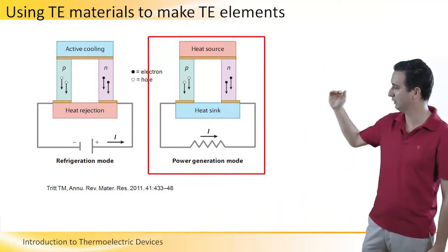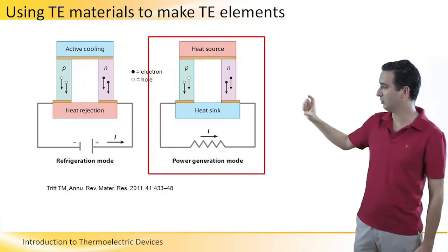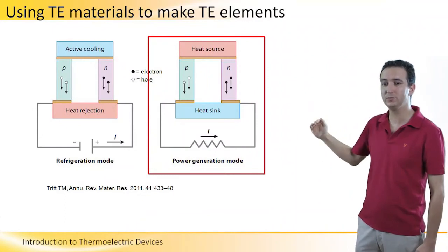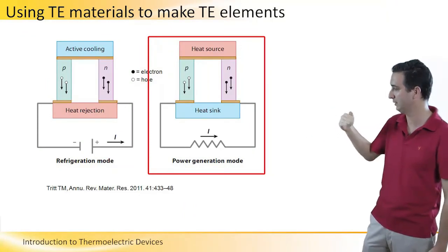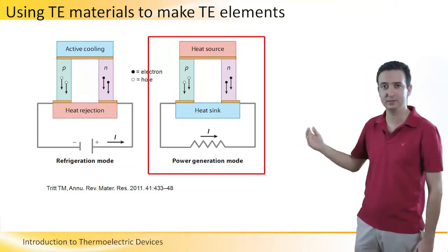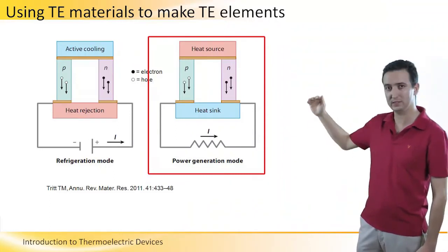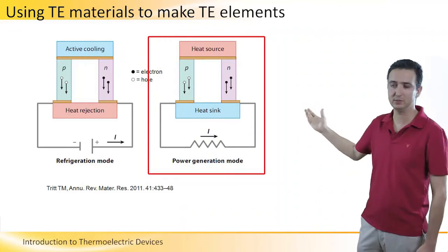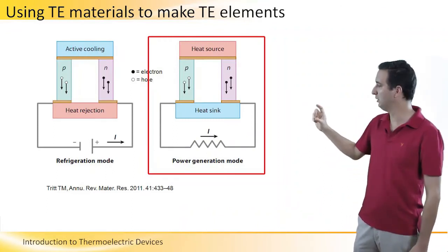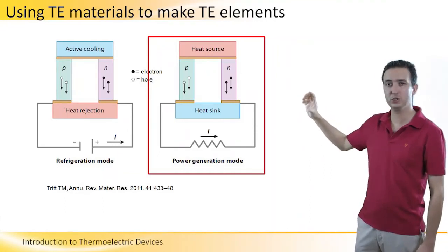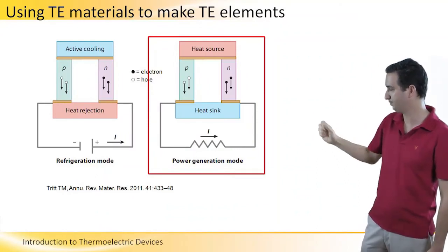And the other thing is that if you take a look at the hot side and the cold side, they are connected only by materials with very low thermal conductivity. These semiconductors, as will be explained later, have very low thermal conductivity. If I would connect the cold side and the hot side by metal, let's say gold, since gold has very high thermal conductivity, I would diminish the initial thermal gradient, so the thermoelectric effect will diminish.